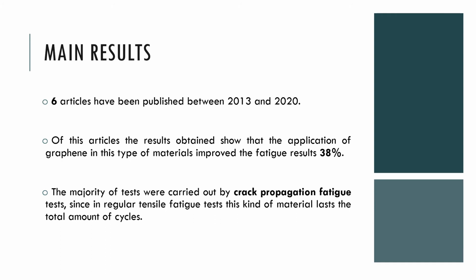A total of 6 articles have been published between 2013 and 2020. Of these articles, the results show that the application of graphene has the ability to improve the fatigue life of the material, with some articles showing an improvement of 38%. The majority of tests were carried out by crack propagation fatigue tests, since in regular tensile fatigue tests, this type of material lasts the total amount of cycles.